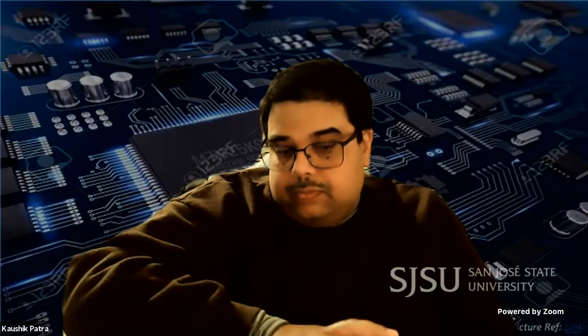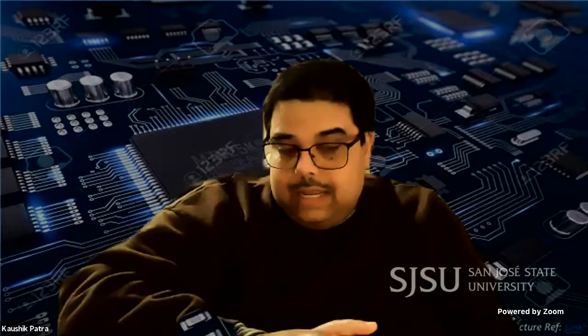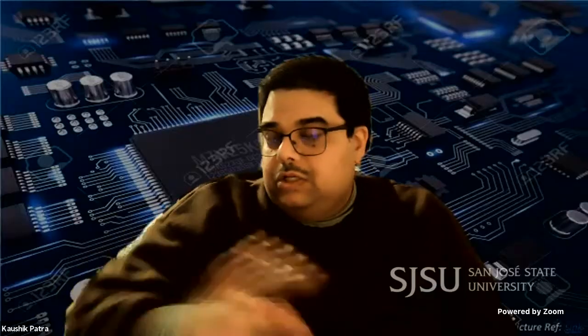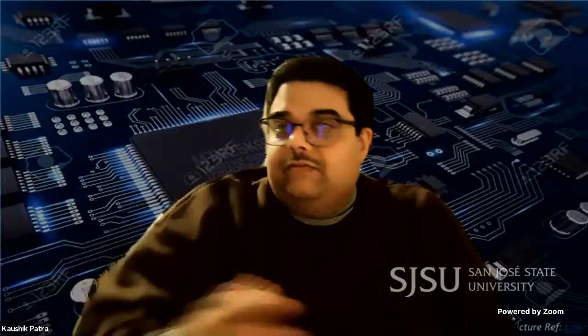You look at the input space and see how many bits you need to represent that many input combinations. Okay, and you see if it covers the whole space, like you need 4 bits and you need to represent 16 different things, then there is no don't care. But if you are using, let's say, 5 bits and you need to represent 24 different things, then you have 8 don't care terms out of that whole input spectrum. Make sense, Matthew?